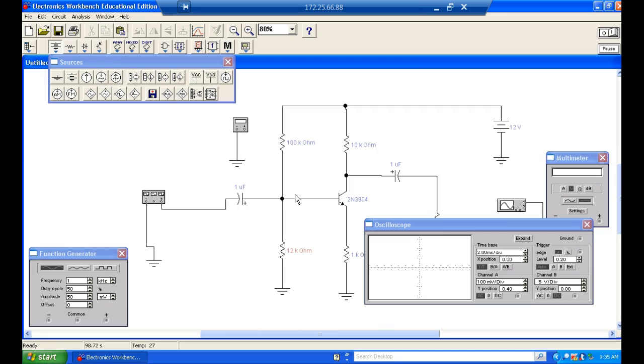Now, it's going to be kind of misleading, but we know that base voltage is going to go way up. Output signal is going to be clipped. It's going to be all distorted. All your biases are going to be off. And this is the trick, guys, understanding these biases to understand what's wrong with the amplifier. So base voltage went up to 1.8 volts, which is all it can do, right?